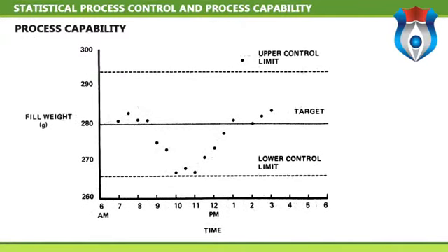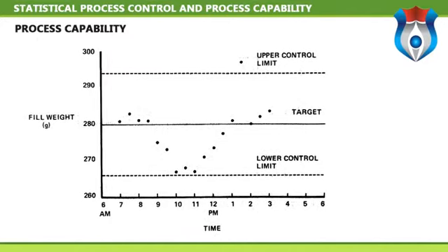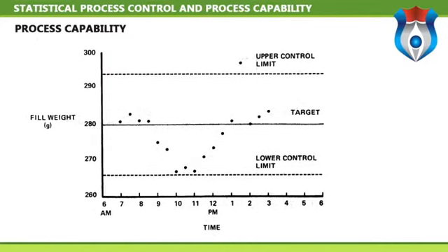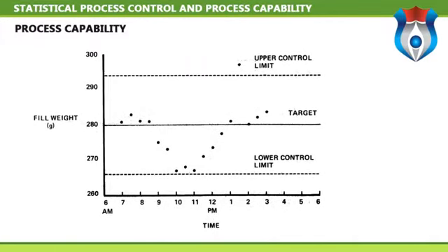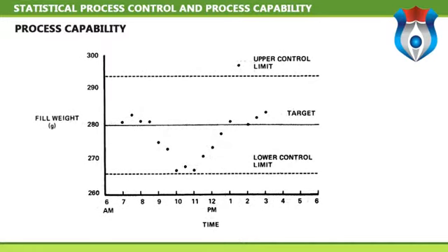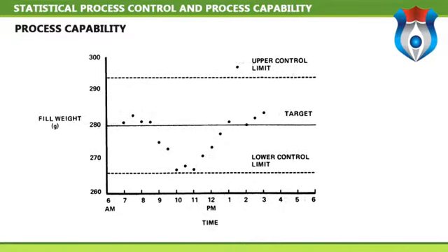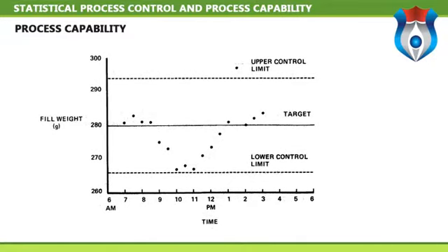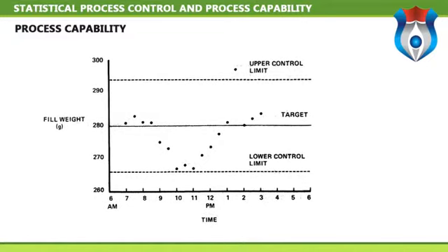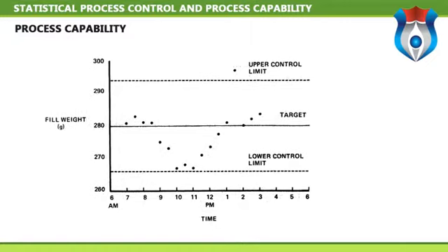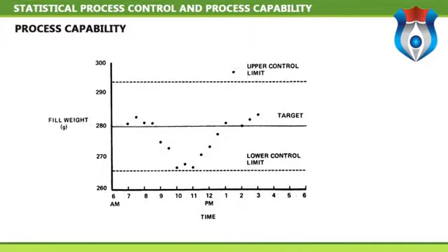Process capability requires that the standard deviation estimate come from subgroups of data, rational subgroups where the variation within them is considered homogeneous. This means that the variation over time will exist between subgroups, but that the variation is homogeneous within the subgroup. Process capability is also the ability of the combination of people, machine, methods, material, and measurements to produce a product that will consistently meet the design requirements or customer expectation.